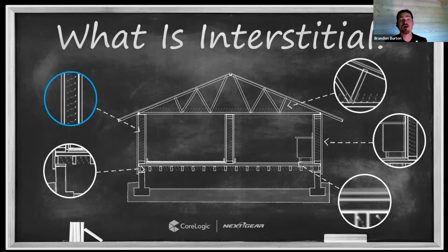And it may not do much for the drywall if the drywall is wet on the back side, or even if the gypsum is wet, especially if the interior is finished with a high glossy enamel paint, right? Or there's some wall paneling or some wainscoting that has encased the interior surface of that wall. In all of those instances, the wet evaporating surface is not being exposed to my drying system. And that's the real question that you want to think through when we talk about interstitial spaces, interstitial cavities. Where is the wet evaporating surface?